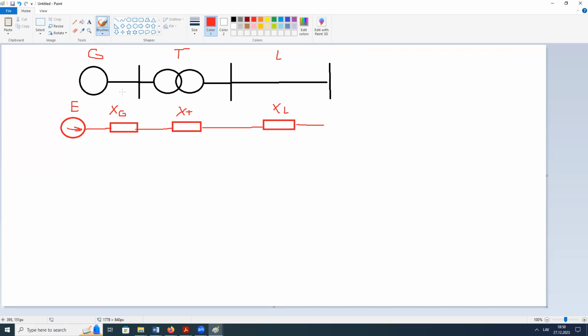How could we understand what is going on in a case of a two-phase fault? What is going on with the faulted phases and what is going on in the third phase? Quite a complicated question. And what is the idea of this symmetric component theory?